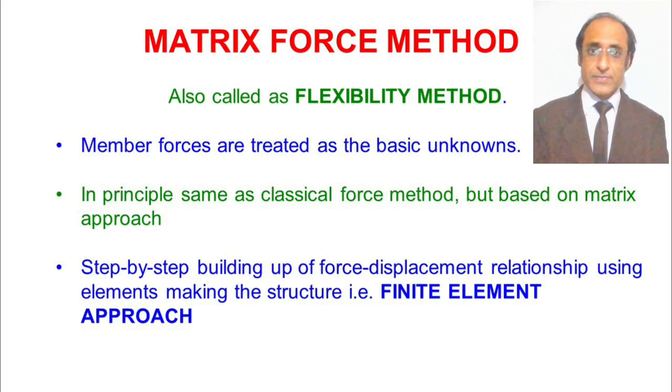We just re-emphasize that in the force method, essentially forces are the main unknowns rather than the displacements. So the external applied loads P, their directions, define the positive directions of the resulting displacements. If we want to get the displacement at a particular point, we must definitely apply a load at that point. Only then will the method give us the displacement at that point.